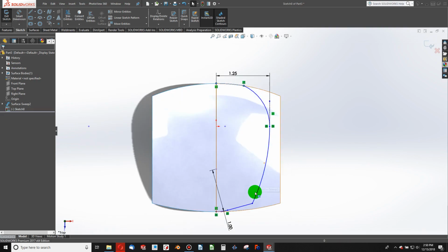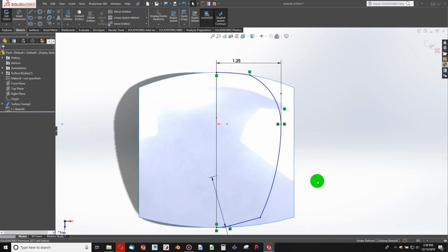So we don't have to make everything completely tangent. The thing to look out for in surfacing is I don't want to have a fillet that will run into something that is tangent, whereas there's a sharp edge in another spot. The fillet won't work. It'll say something like cannot fillet lateral surfaces or something like that. So if you get that error, you're probably getting a sharp edge that's running into something that becomes smooth later on.